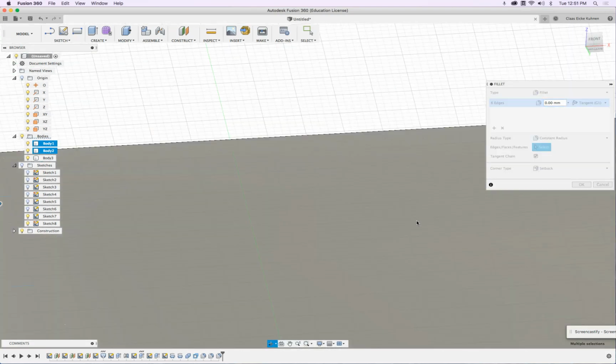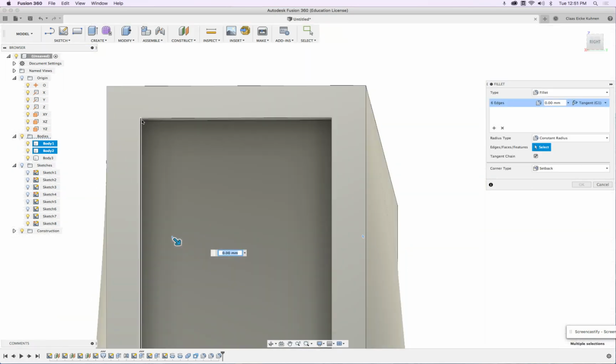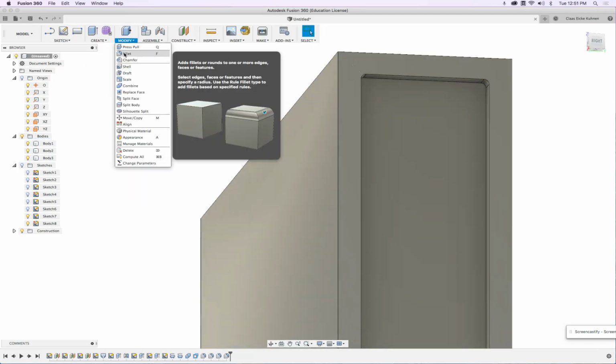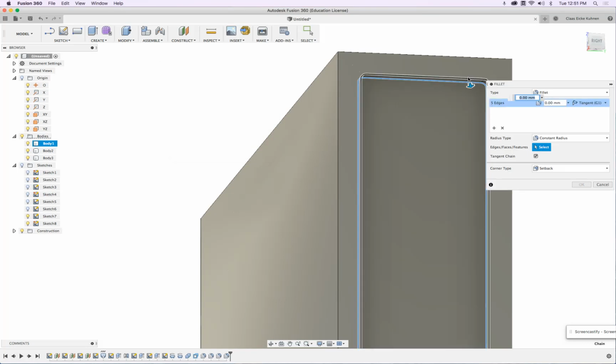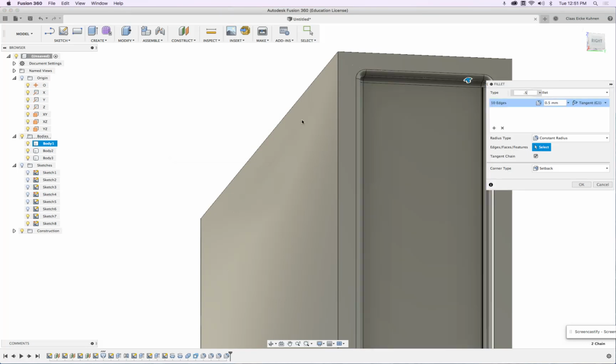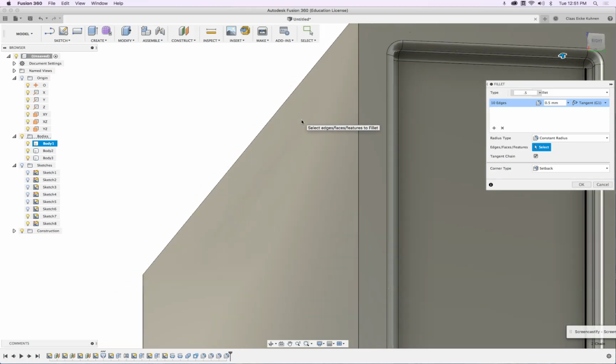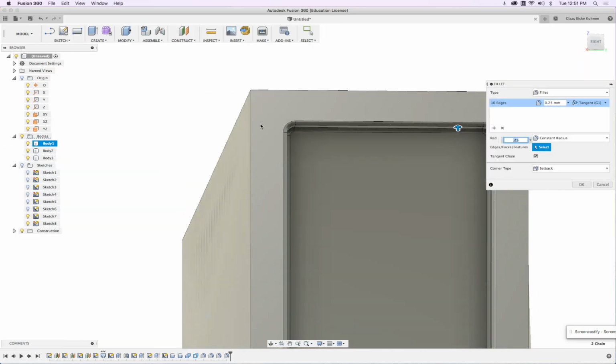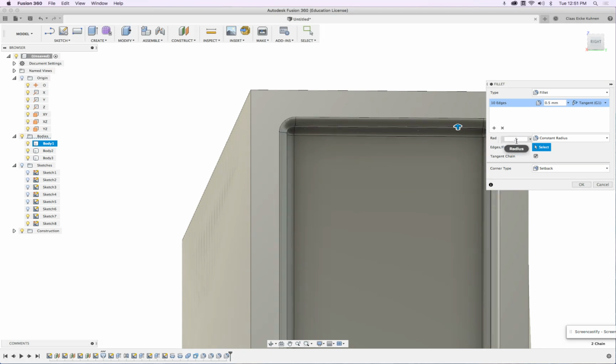There. This one and this one, 0.5. Very good. So we pre-round those corners, and then via the fillet command we can select this edge and this edge 0.5, and there we see we do this rounding, and maybe not 0.5, let's say we go with 0.25, so that this still remains nicely round. In this case here you can see this is too tight.